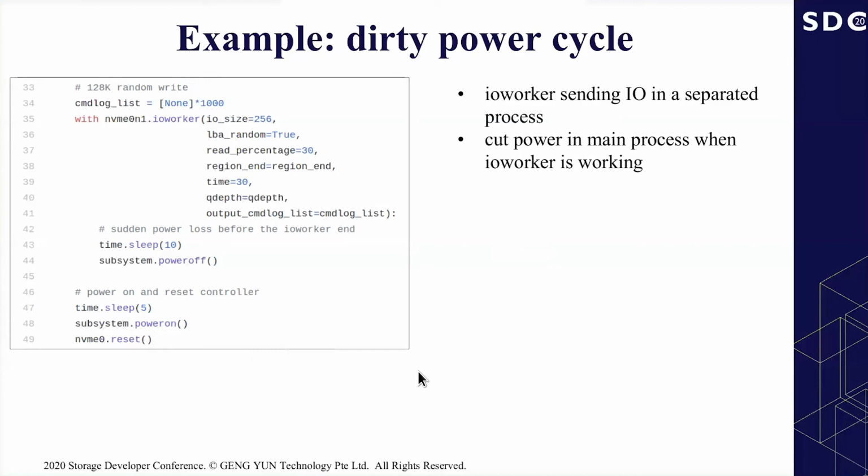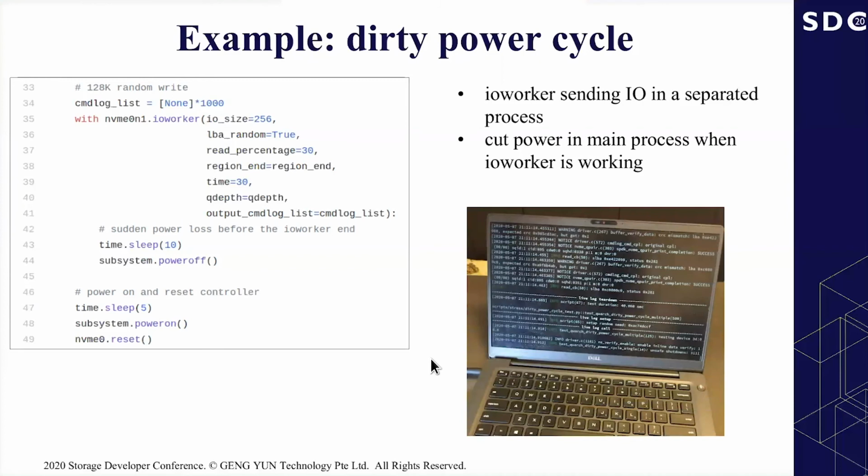Because Pynvme uses its own driver instead of the kernel's NVMe driver, the kernel will not do anything to protect the SSD before dirty power loss. Everything is still under control of the test scripts. In this picture, we can run these dirty power cycle tests on a laptop without any dedicated hardware.